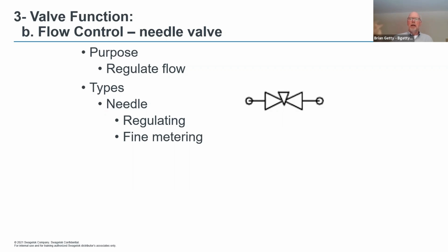Take one of those nozzles, block it. What happens to his pressure? His pressure starts to climb. Take another nozzle, block it. What happens to the pressure? It continues to climb. Now, if he's got something in that system which is sensitive to higher pressure, at that point, he could wind up creating damage in his system.